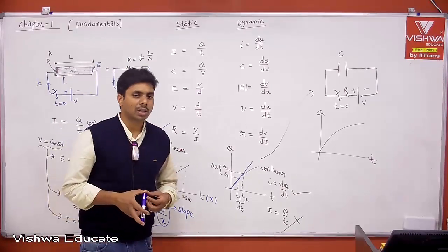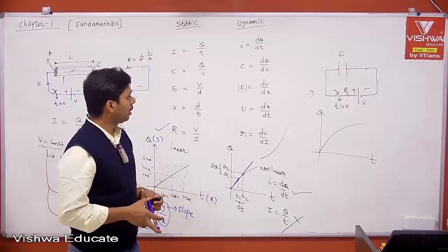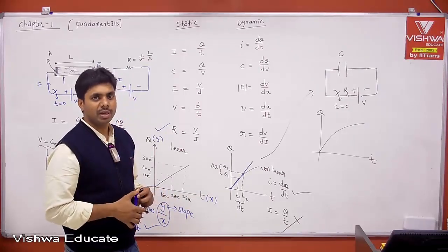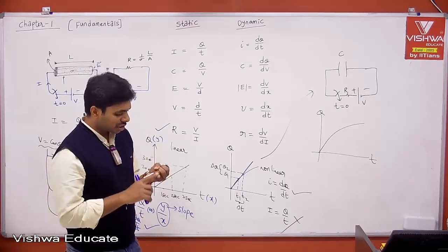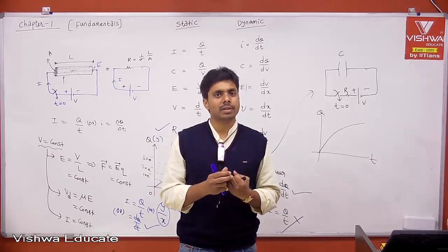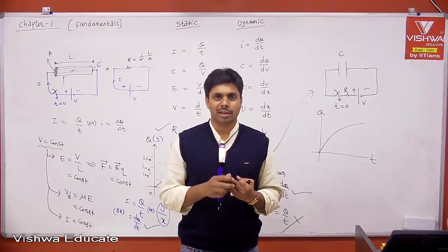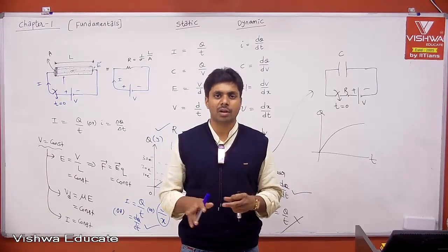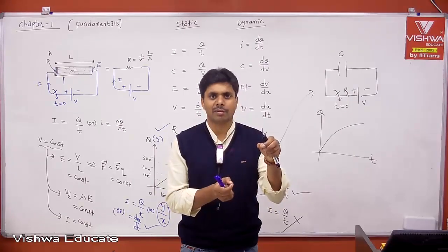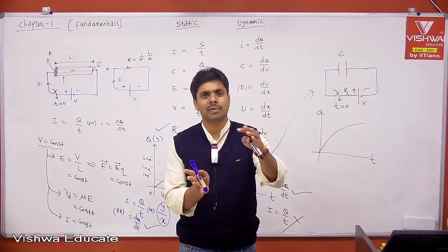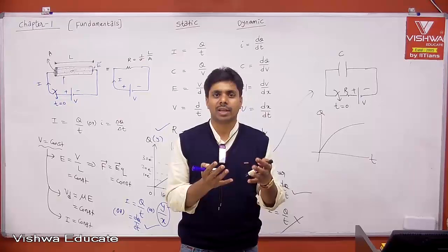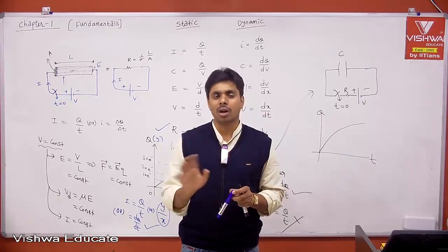Therefore, the conclusion with respect to analog circuits where we use all semiconductor devices with PN junction, right? PN junction diode, BJT, MOSFET, right? All these three elements are non-linear, therefore the definition of resistance is by default dynamic resistance. When I speak about the input impedance of an amplifier, because the input impedance of a BJT amplifier is indirectly the input impedance of the BJT device, we should take the dynamic definition, not the static definition.